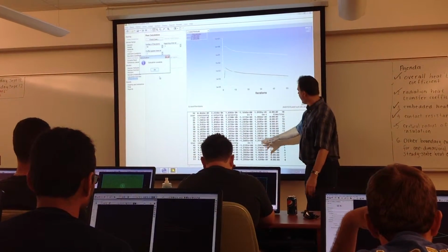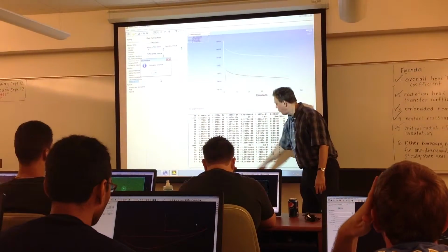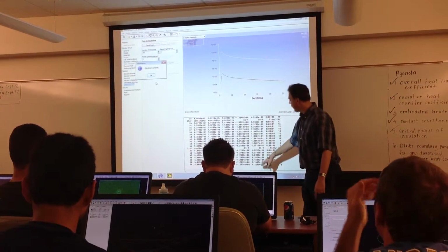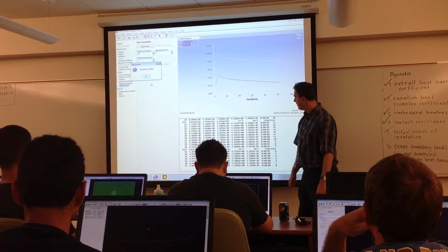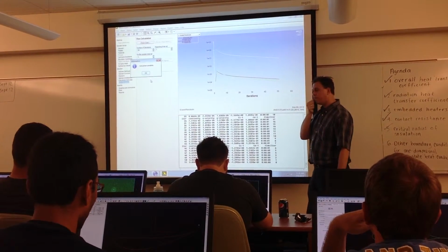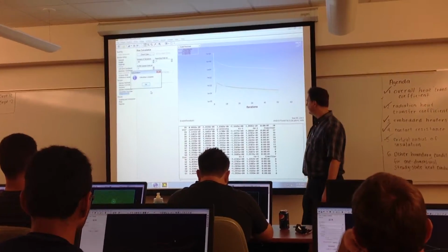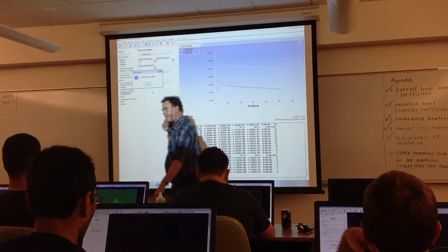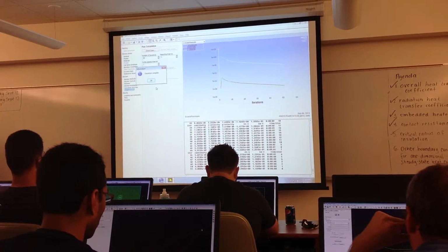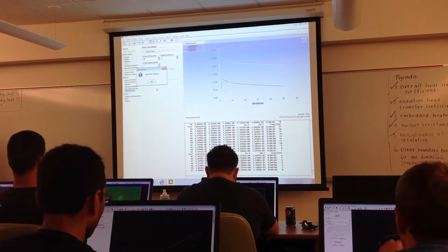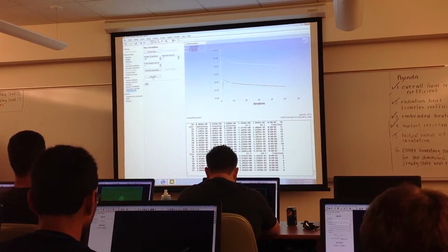And then the lift and drag coefficients here. Look at the lift coefficient, 1.3, drag coefficient of 0.011. That's like a lift drag ratio of, what, 11, 12? That's not unreasonable. A lift coefficient of above 1 is certainly attainable with an airfoil at high lift, especially an airfoil like this. So I can run this a bit more.